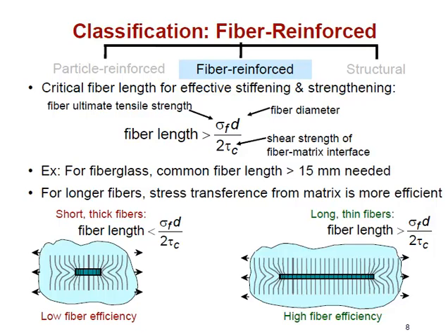And it says, here's how long the fiber has to be so that the matrix can transfer stress to it sufficient that I could break the fiber with the transferred stress. So if you are able to transfer enough stress that you can use the full strength of that fiber, as evidenced by you could break it, then you're getting the full efficiency of the fiber. And that's literally what that formula says. So since fiber reinforcers tend to be a bit on the pricey side, you don't want to use a higher volume fraction of them than you really need.